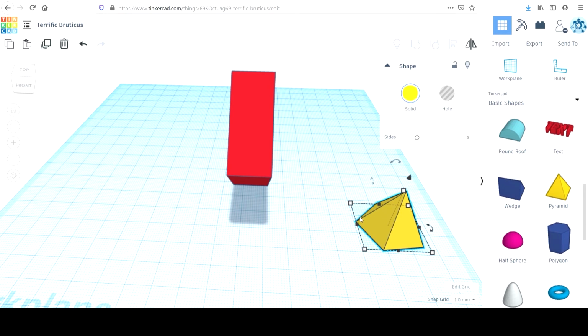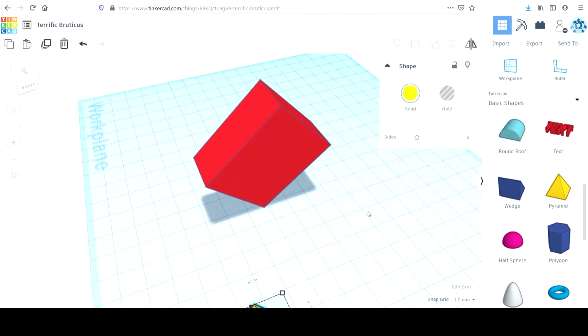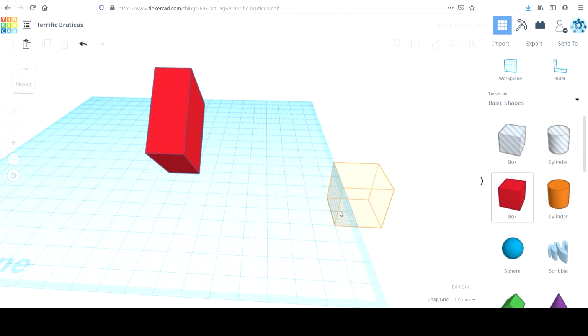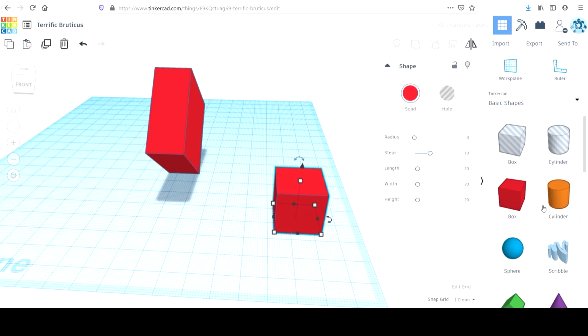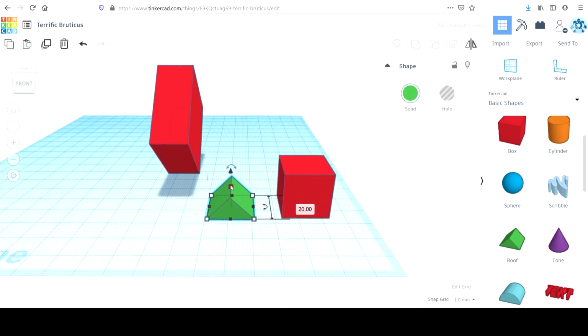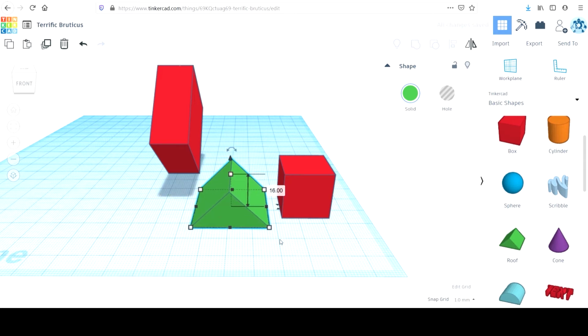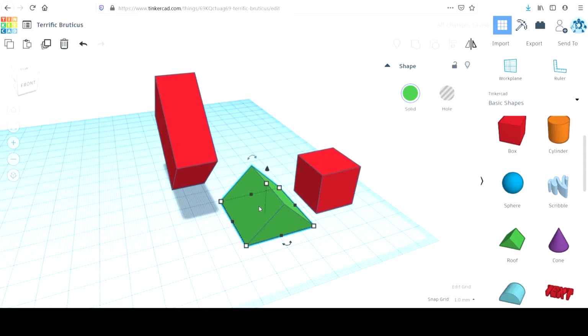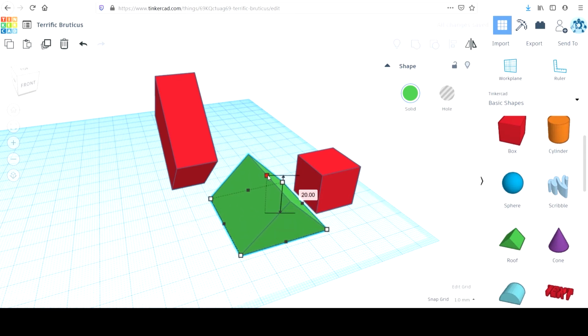The next command we're going to be talking about is the group command. So for example, if I wanted to make a little house, I could take a couple of pieces and combine them together to give a more realistic, solid structure for my house. Could increase the size there. In that instance, I held the Shift key, and that will scale the entire object larger or smaller uniformly, which means there's no distortion. The same proportions are going to remain as I scale it.